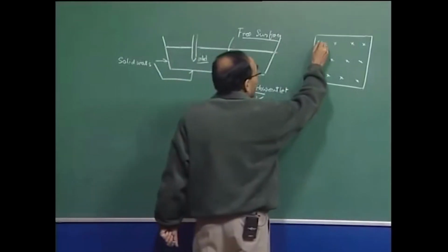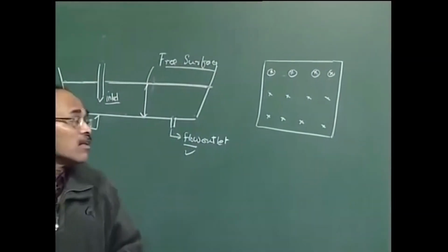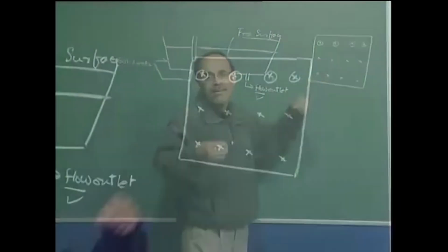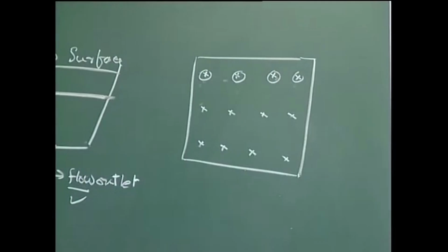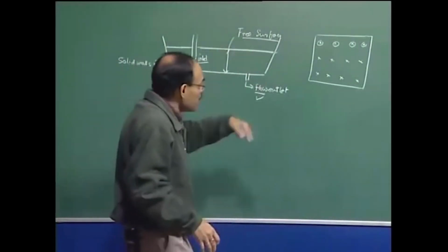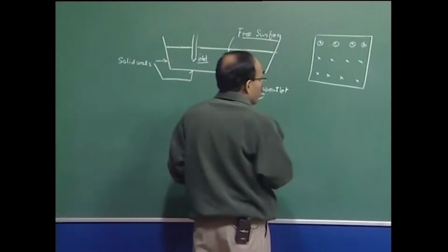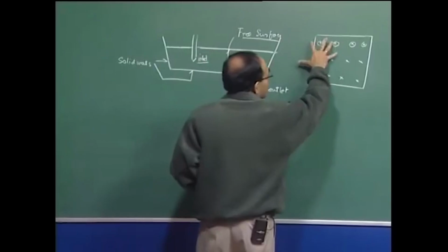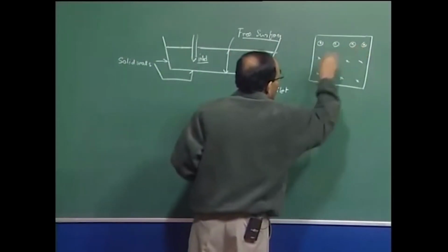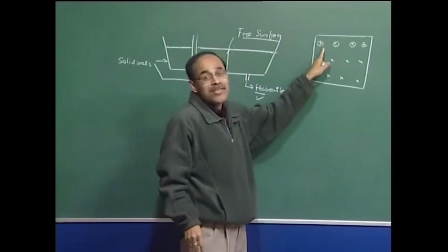So now I can have a solution here, here, here, and here. How do I know these points? These are the points that the person who is solving desires. For example, I can say I need only 16 points on which the velocity distribution is needed. Someone else may say, no, I don't want 16 points, I need 160 points. So it is the person solving the equations, the modeler, who decides at how many locations he is going to need the solution. These points at which the solution is sought are termed the nodal points or the